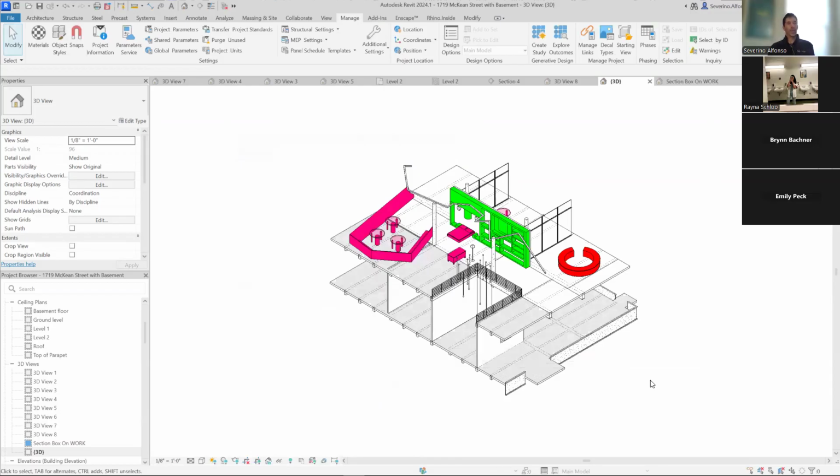Okay, so that's the way you do it. It's not an easy one, and I mentioned that it's a little bit of an advanced thing, but changing visibility in graphics options through filters is not an easy one, but it is a powerful one. And you don't have to see it only as a way to affect diagramming colors, but in general, if you want to hide some types of floors and not other types of floors, depending on when they were constructed or the type of materials that they have, you could always create your own filters to do that type of operation, okay?